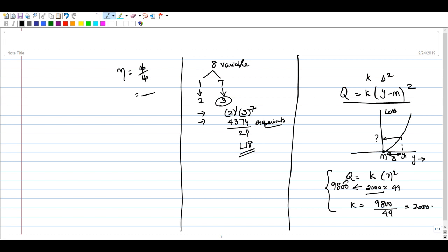Then the second point is the part must be of a different material or must be isolated from all other parts assembled, for whatever reason. It could be insulation, electrical isolation, vibration damping and stuff like that. And the last one is the part must be separate from all other assembled parts, otherwise the assembly of the part meeting one of the preceding criteria would be prevented. Unless the part is a different part, the points that we have mentioned in 1 and 2 will be violated. That is the third point.